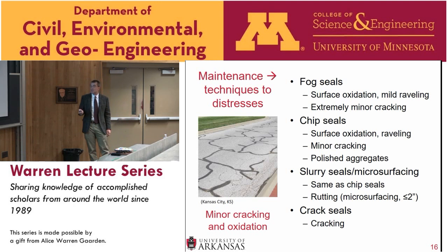And then the pavement surface is very light colored, and that means it's been oxidized. So the asphalt binder has reacted with the oxygen in the air, and it's aged it. So instead of being sticky and cohesive, it's turned brittle and dry at the very surface.